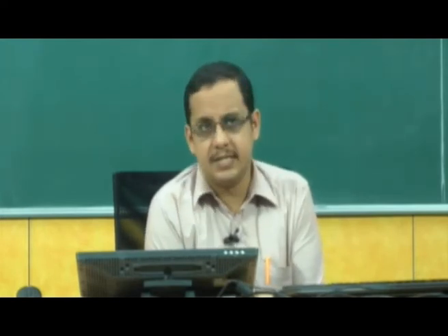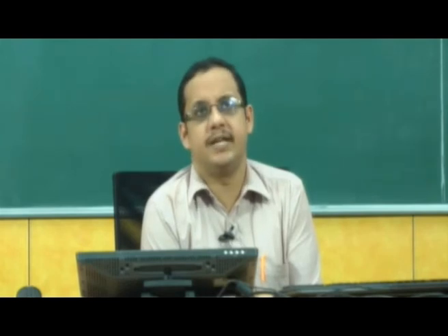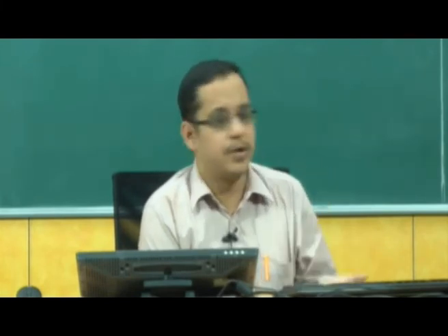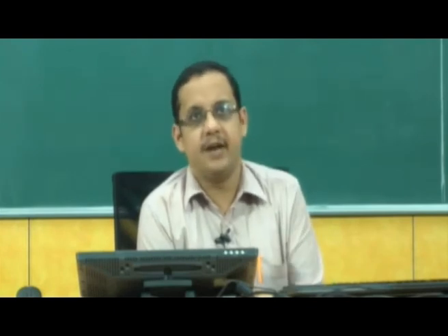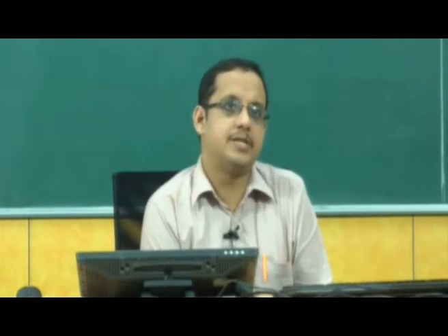As for CEC, I think we have just answered your question. The position of unbalance is detected in an experimental setting using some instrumentation which I cannot talk about here. Here we have talked about how to detect. It is not about how to locate that position. If you want, that can be done with some experimental techniques. There are balancing machines available for this purpose. The principles of how the balancing machines work and what sort of measurements have to be done will take us too far out of the scope, but if you want, I will definitely post some literature on this for your supplementary reading.